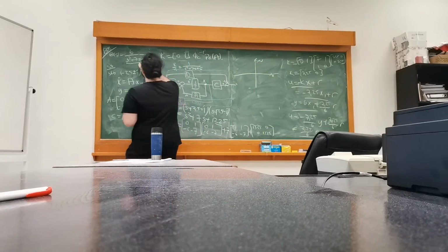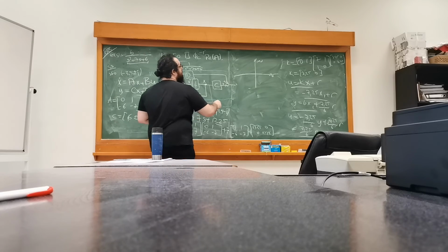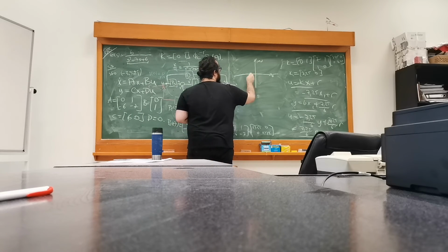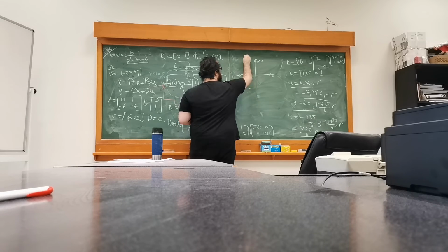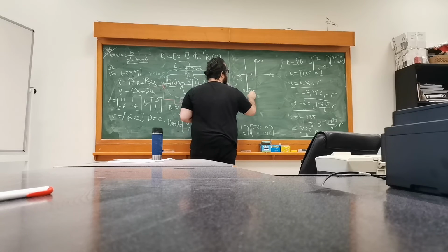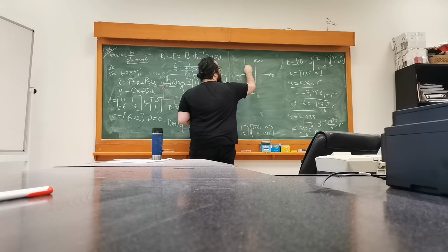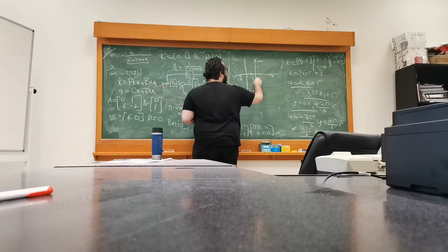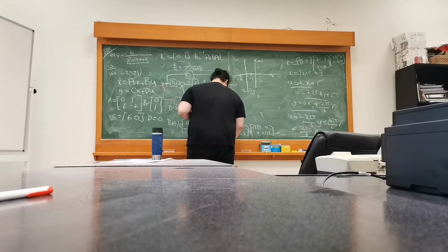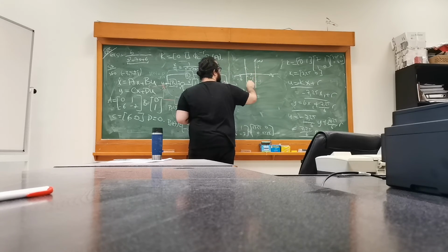So we have minus 1, minus 6. They meet here. One goes up, one goes down. And this coordinate here is minus 7 divided by 2, minus 3.5. So therefore, this is i, this is minus i. Your point is on the root locus here.